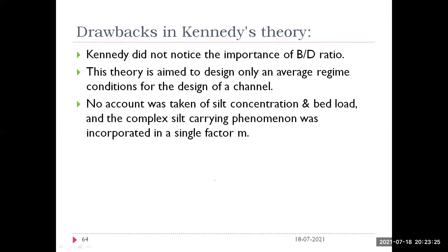Also, he has not given an account for the silt concentration and also the bed load. He has not taken them into account. The complex silt carrying phenomenon was incorporated in a single factor m. Because he did not give more importance to the silt concentration, he just included a single factor m. That is one of the drawbacks.